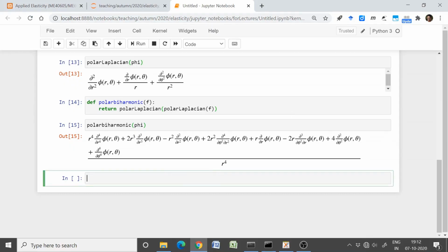So first of all, our first job is to convert the sigma xx, sigma yy and the sigma xy, those things in terms of the derivatives of r and theta. And further along, we'll transform the stress matrix itself from the sigma xx, sigma xy and sigma yy to the sigma rr, sigma theta theta, sigma r theta. All right, so we have quite a few jobs in our hand. Let's address them one by one.